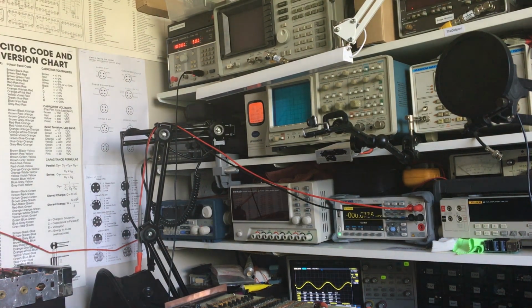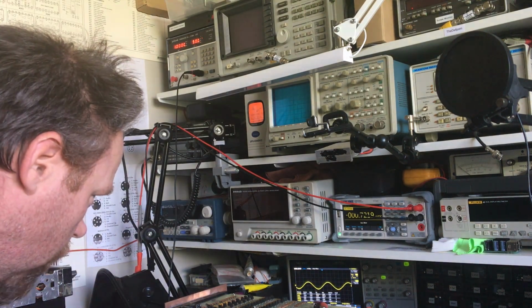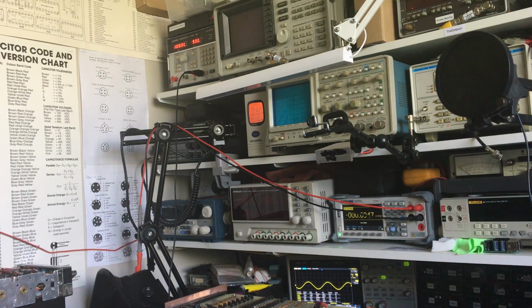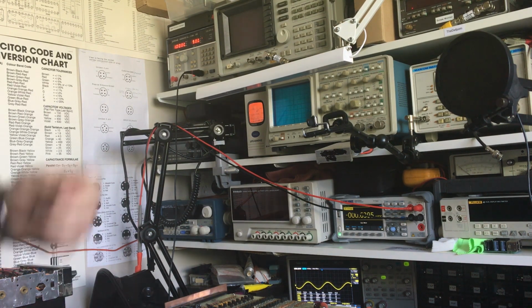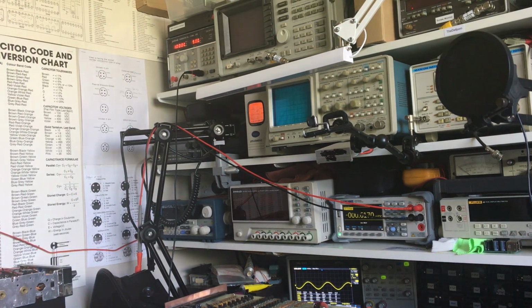So yeah, that's all right there. Change ranges, disappears, and that is 1 kilohertz. So the quadrature output there is also working okay at that frequency. If I change ranges on here, it's all stepping okay, as it should. Right, that's working alright. So now let's do 100 hertz instead.